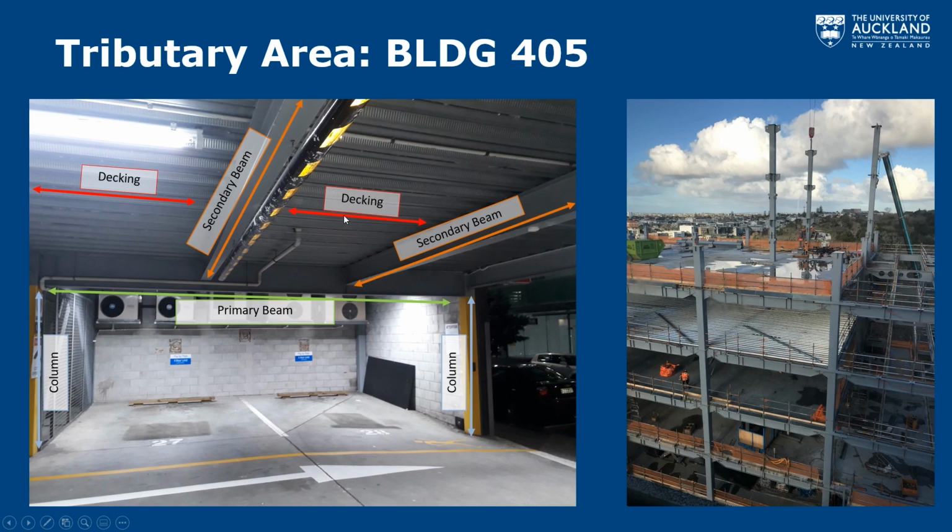And so the load path for this is that if you've got a piece of load which is here in the middle, well, it's going to get spread in one way along the deck. So it's going to go parallel to the ribs, because that's the stiff direction. If we were going in the orthogonal direction, it'd be like trying to bend a piece of corrugated cardboard parallel to the corrugations. It really doesn't have any good strength and stiffness there, and so it'll bend into a U. While if you think about trying to bend a piece of corrugated cardboard perpendicular to the corrugations, it's very stiff and very strong. And so it's the same thing here.